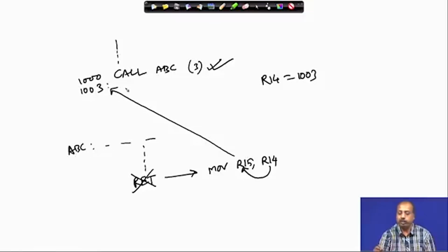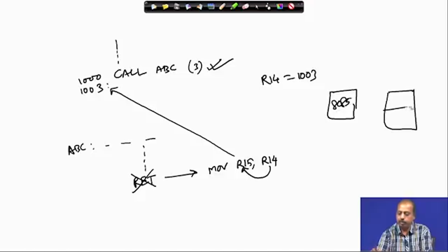So, if you consider, say, the 8085 processor, and you have this as the memory, a part of the memory is defined as a stack, and the top of the stack is pointed to by the stack pointer. Whenever a subroutine call is made, the PC values are saved: PC low and PC high are saved onto this stack, and for returning, these values will be popped out from the stack.